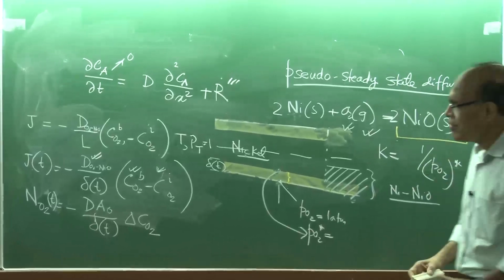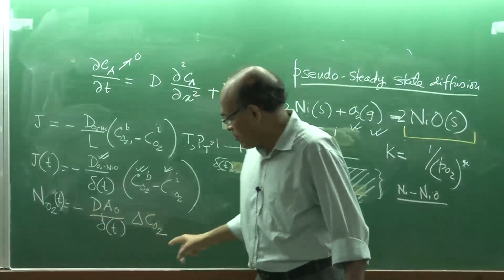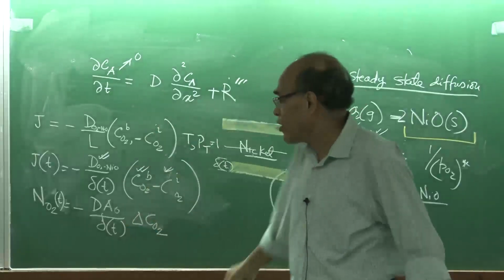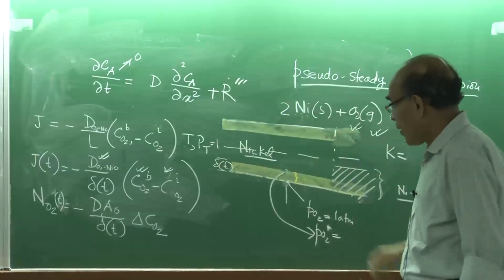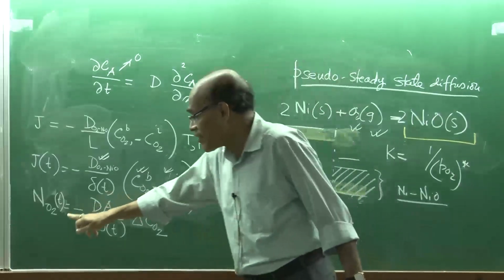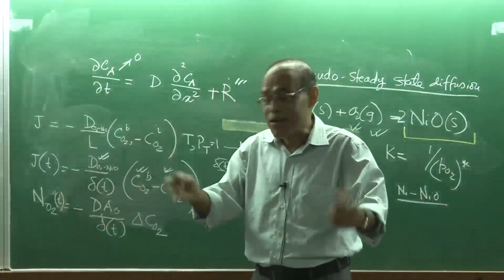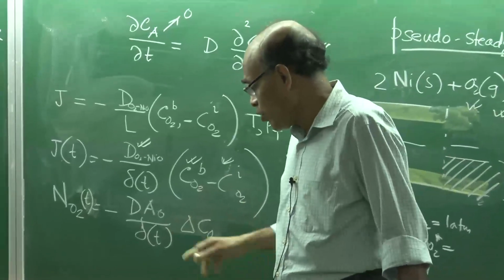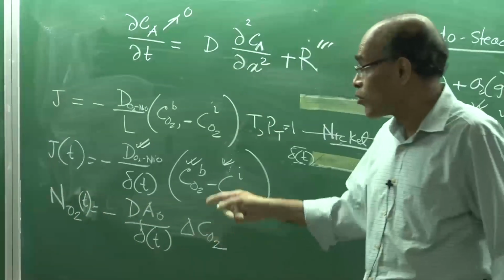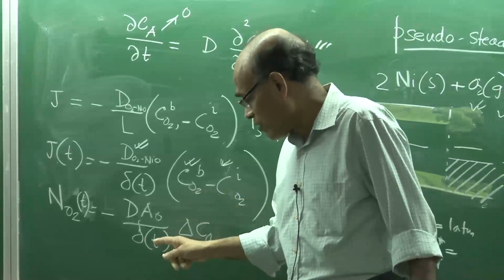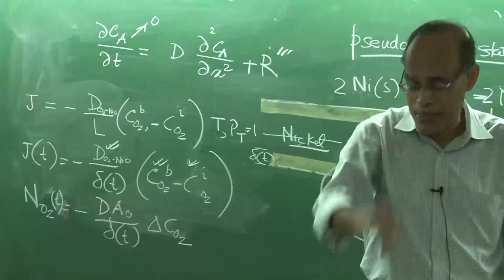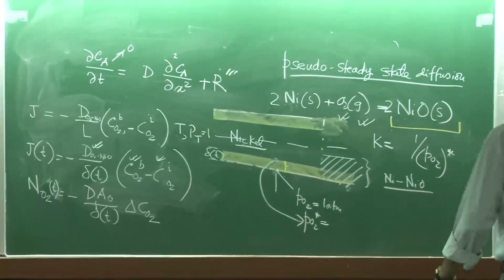And how have I applied it? This is a straightforward application of the steady state one-dimensional diffusion problem solution. But we must understand that we now get not a steady state flux, but an instantaneous net rate of transport. The instantaneous net rate of transport can be calculated provided one knows the instantaneous path of diffusion through which oxygen is moving.